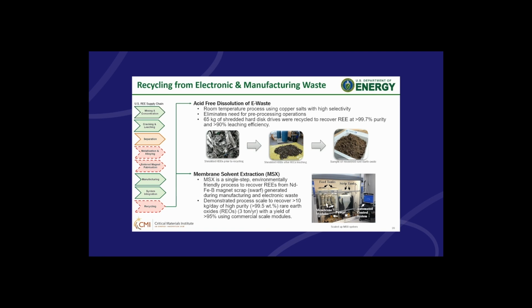And then membrane solvent extraction is pretty interesting too, because conventional solvent extraction in industry takes hundreds of stages of mixers and settlers. This is just a modular system that you could bring to a recycler. You can just keep regenerating or reintroducing the aqueous phase into the membrane and keep getting the material out, so you don't have to build many, many stages of solvent extraction mixer settlers. They were also able to tailor the extractants in this system, so one system is focused on battery materials, and this one is focused on rare earth elements.